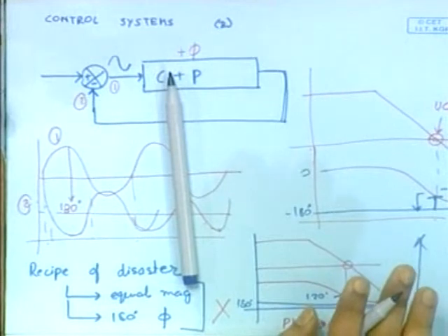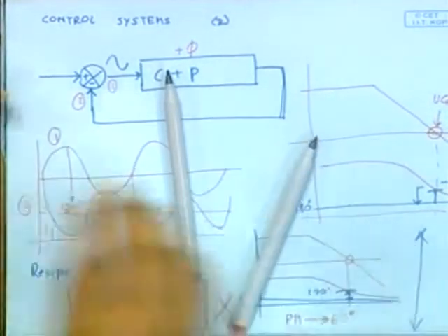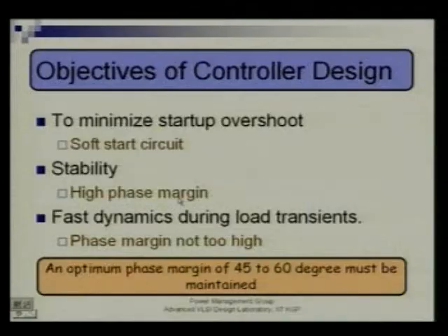That's the concept. So when I look at stability, the higher the phase margin, obviously, the more stable your system is. Suppose if I say that this is 100 degree at this point, you have room for an 80 degree phase disturbance. The higher the room for your phase disturbance, the more stable your system is. Now I'll ask you, is it good to have a very stable system? When I say a system is stable, there may be a threshold.